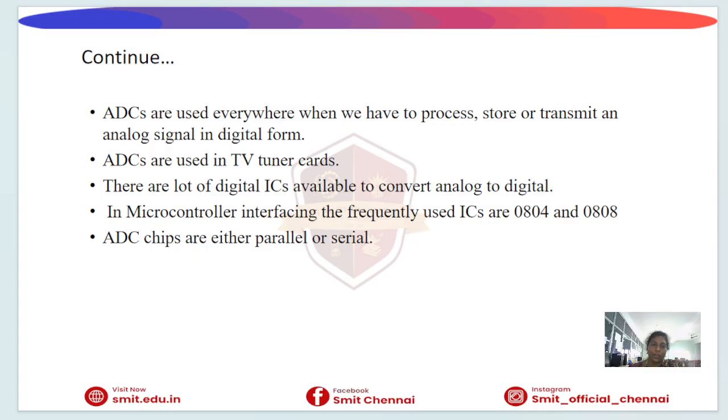ADC is a very important component. Microcontrollers can process only digital data, but most sensors generate analog outputs. If we have analog outputs, we cannot find the value of the output, so we use the ADC because it converts the analog output into digital format. Therefore, the ADC acts as a bridge between the sensors and the microcontroller. The analog world is the sensors and the digital world is the microcontroller, so because of the ADC, the microcontroller receives the output in the digital world.